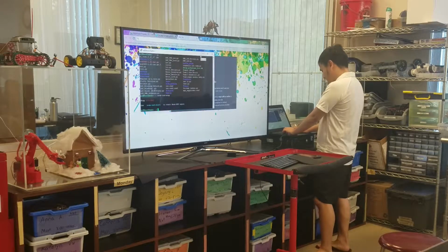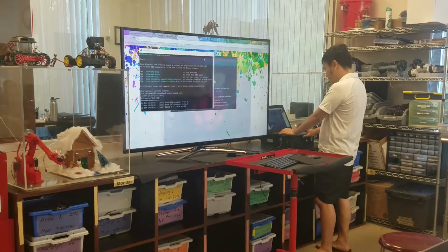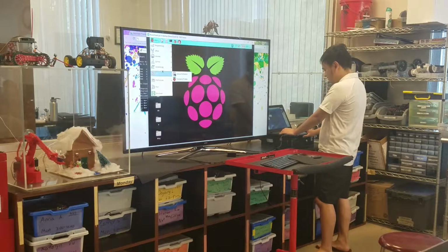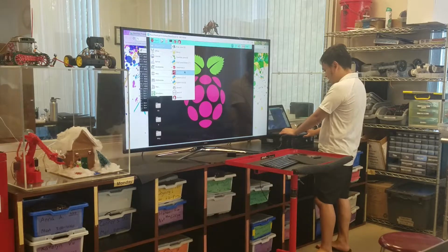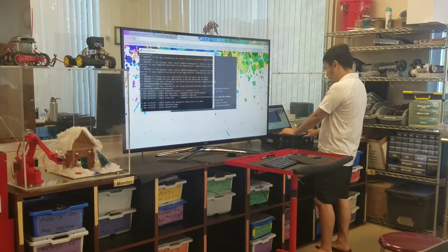In here I'm going to enable Node-RED in my Raspberry Pi. I have to start it first. To start Node-RED on your device, you can simply go here, click on menu, accessories, programming, and click on Node-RED too. It works the same way, but PuTTY is faster. That's it.